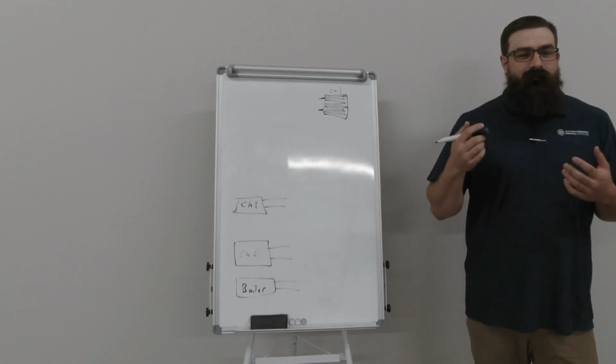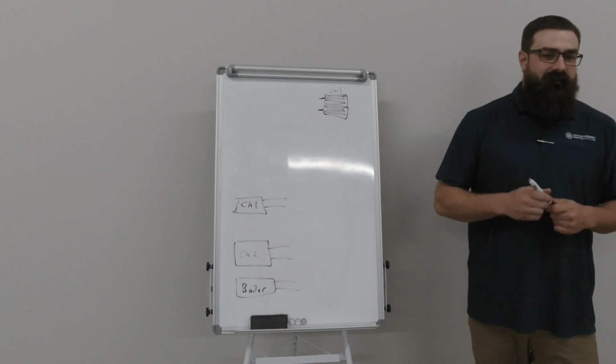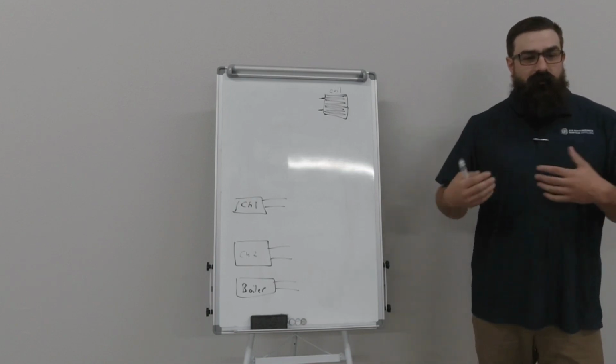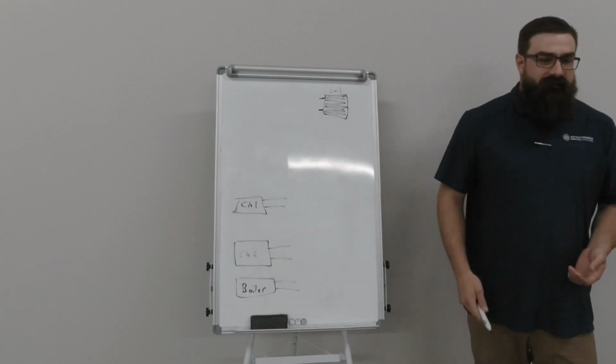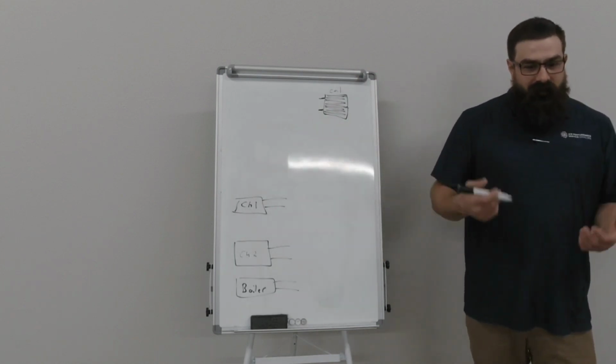Building engineers and property managers and stuff, sometimes they get confused. You say supply, what we mean, they might not mean. Somebody may have labeled the thing wrong. You never know. So I like to stick with entering and leaving.